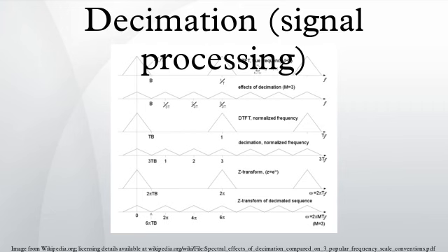In a general-purpose processor, after computing y[n], the easiest way to compute y[n+1] is to advance the starting index in the x array by M, and recompute the dot product. In the case M equals 2, h can be designed as a half-band filter, where almost half of the coefficients are 0 and need not be included in the dot products.